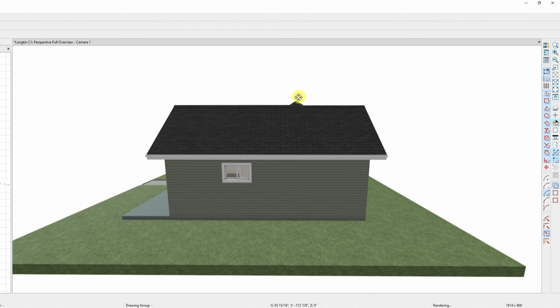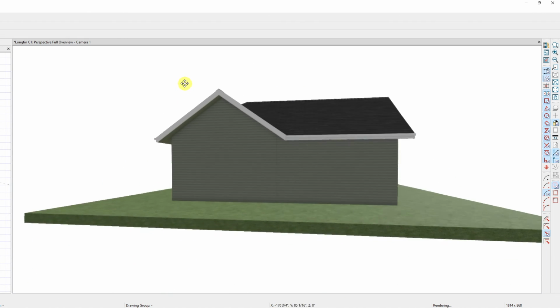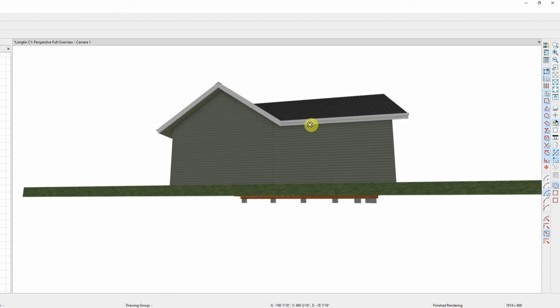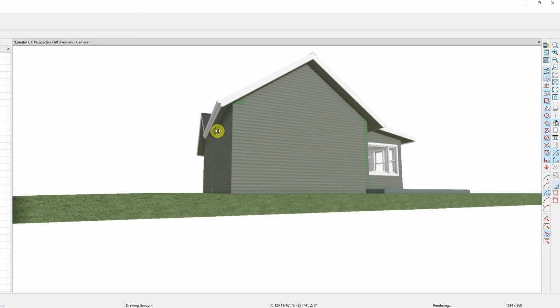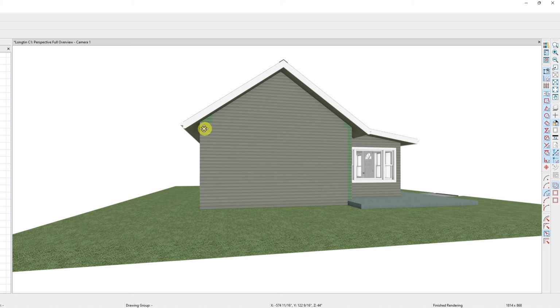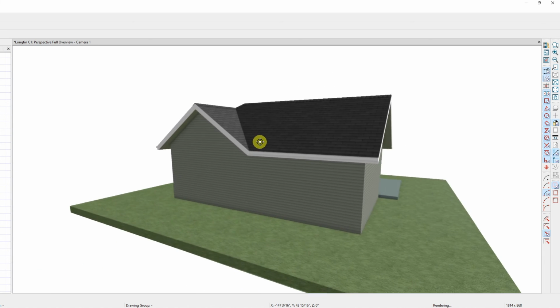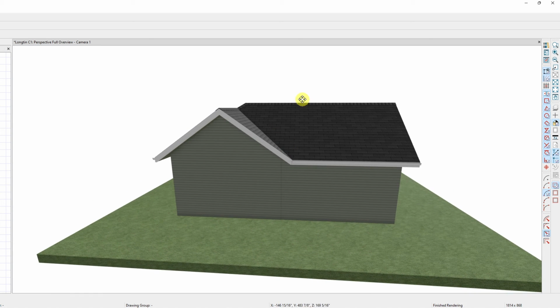So, got a height issue there. But I gotta figure out how to fix it without screwing this up. So maybe I need to run by the site tomorrow and see if one of these has a shorter overhang. Because if this drops, it needs to be shorter overhang to still hit that portion.